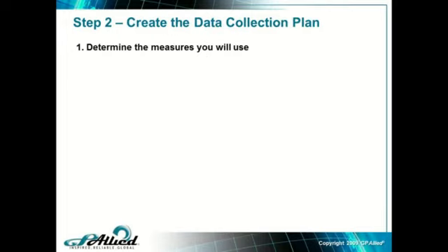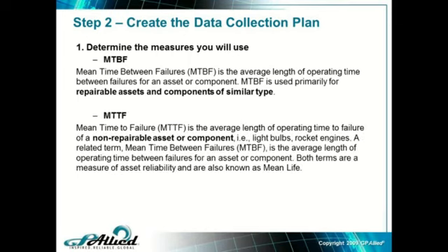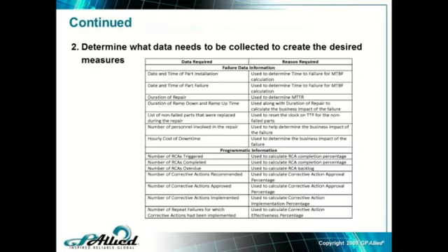Next is create a data collection plan. So we know what we want to collect. Now we want to determine what data we need to collect. So we want to know what measures you want to use. It could be MTBF, okay? Could be mean time to failure. You have to determine that. In ISO 14224, this is some of the information that they have in there that needs to be collected to give you the desired results. That's why I say that ISO 14224 is a great place to go to.